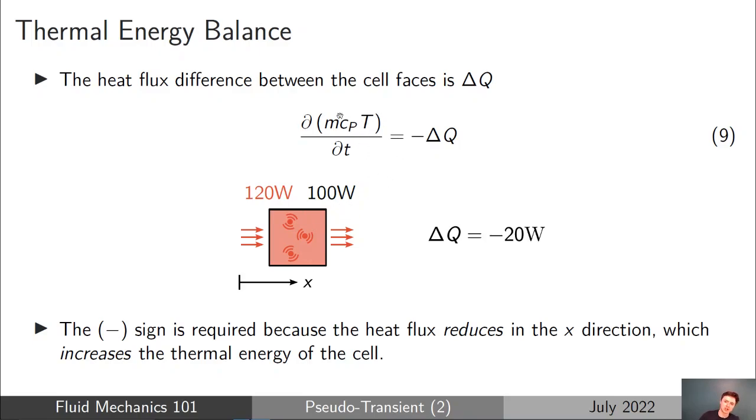And even intuitively, just looking at this quantity, if this element of bar has a large specific heat capacity or a large mass, what that means is that for a particular difference in thermal power between the left and the right end, the temperature increase is going to be very small. So if we have a large specific heat capacity, the temperature difference or temperature gradient in time needed to balance the difference in thermal power between the left and the right ends is going to be very small.